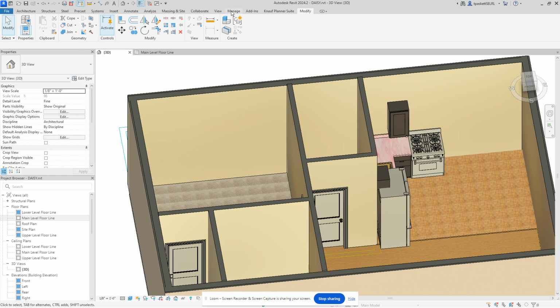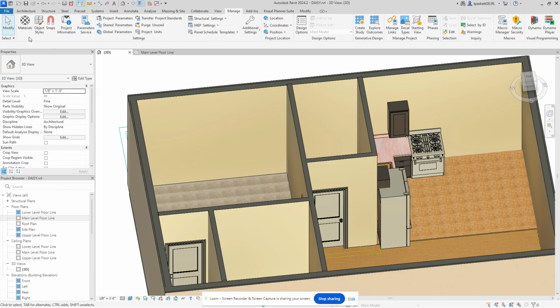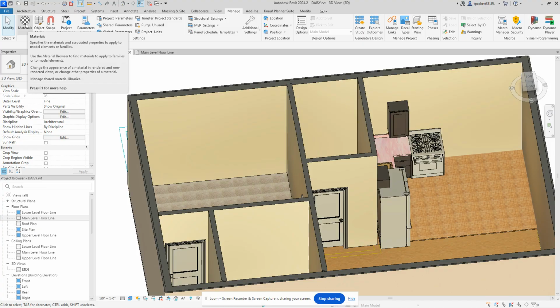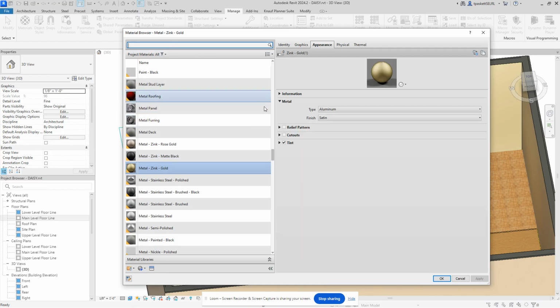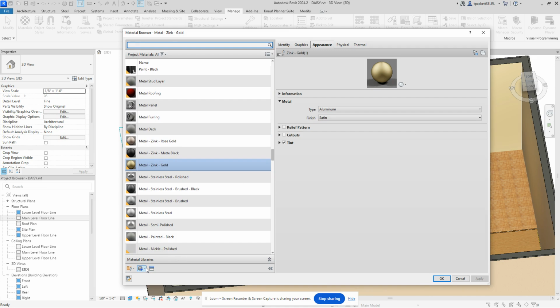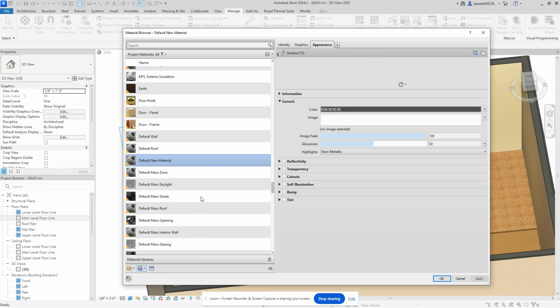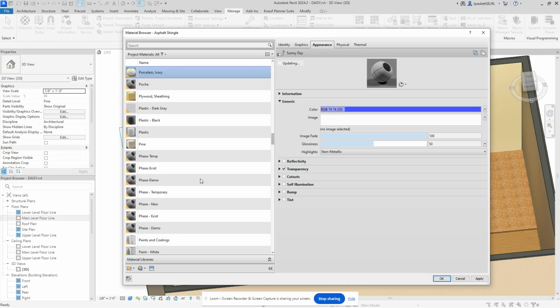We don't spend a lot of time in Manage because they can mess up the program pretty hard here. So in Manage is where all of the settings are for the class, for everything in Revit. The very first one is Materials. So we then go to Materials and create a new one. And now we can get there on most things on the fly, but Paint is the one we can't. So I click on Materials. Oh, well, it's just here. This is the same library I've been using. It's not any different. So I go down and make a new material, and then rename it first before I go on. It'll then be labeled as paint.